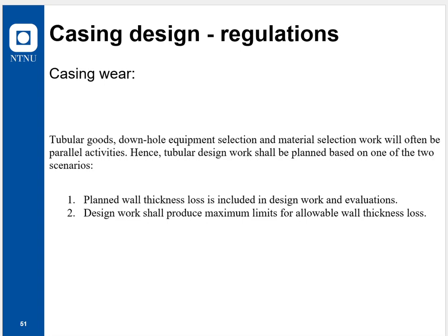Planned wall thickness loss should be included in all your load cases. And typically what you'll find when you're doing analysis is that a good software like Landmark from Halliburton says that your acceptable wall loss can be this, and that's in your plots and your curves as an option if you want it.